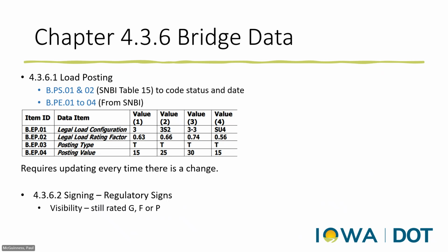On the load rating evaluation section, this has changed somewhat. There's now multiple places to enter multiple truck types. It has the classic AASHTO or FHWA rating vehicles pre-coded in there, such as the 3, 3S2, 3-3.